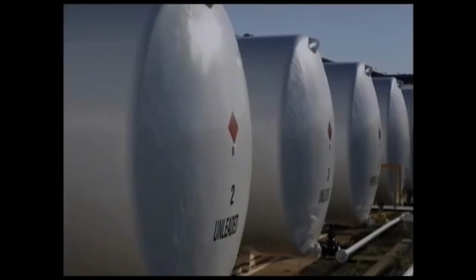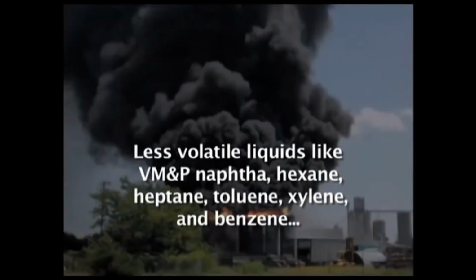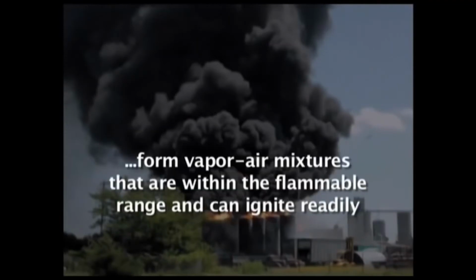That's not so with gasoline, which is highly volatile and usually produces a vapor-air mixture that is too rich to ignite inside storage tanks. But the CSB noted that less volatile liquids, like VM&P naphtha, hexane, heptane, toluene, xylene, and benzene, form vapor-air mixtures that are within the flammable range and can ignite readily.